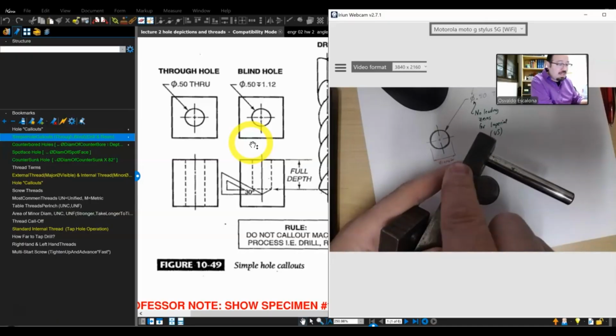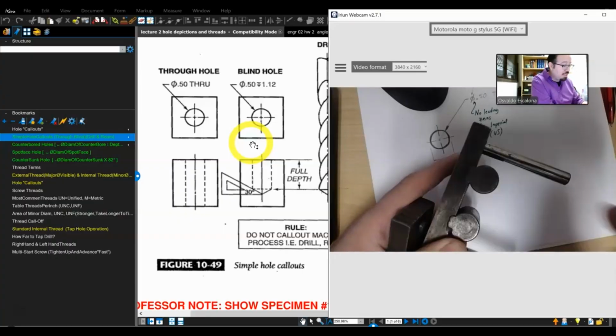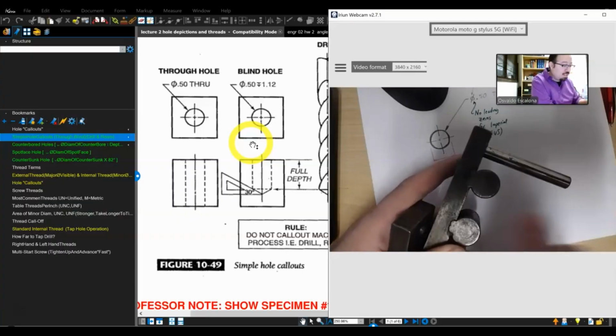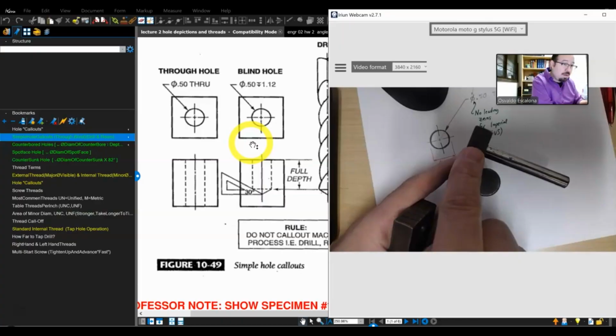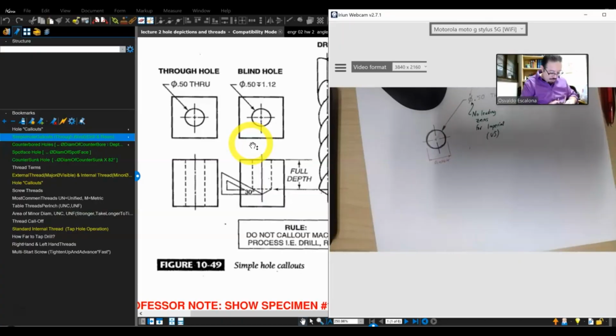The way you make it happen, you warm up the part, you heat it up so it expands through thermal expansion. Grab the pin and push it in, and once it solidifies, it won't come out. That's what you do. But you guys notice, this is an interference fit. At this point, when you're doing an interference fit, you want really good precision, really high accuracy, really small changes. And the way you do it, you get yourself a reamer.